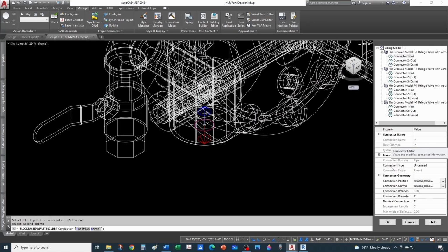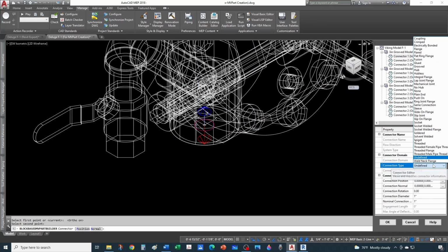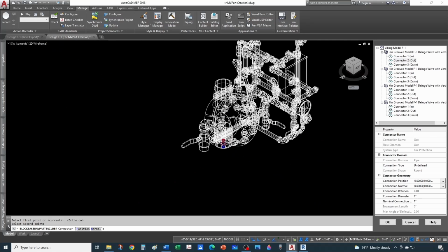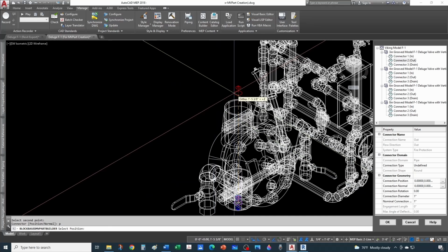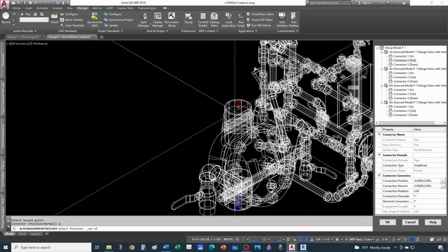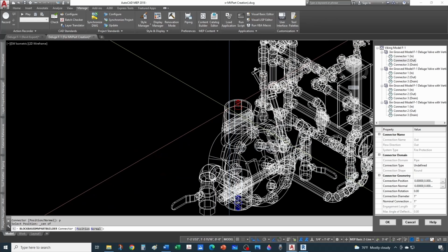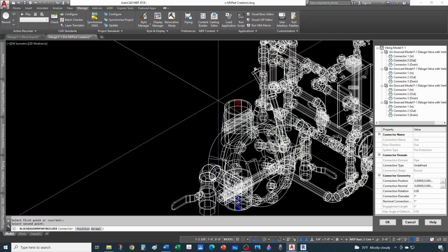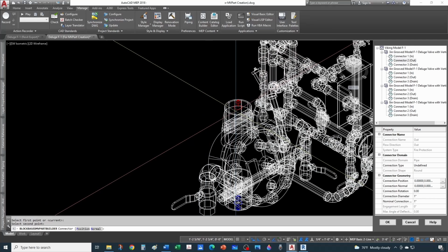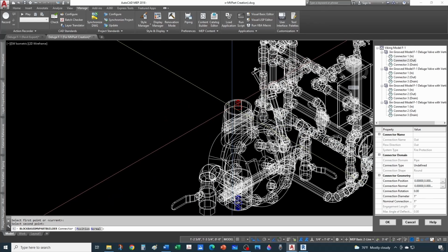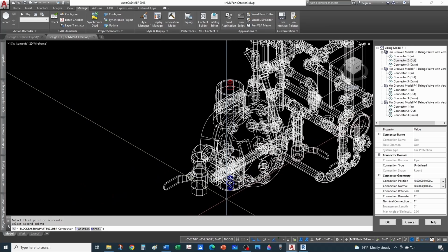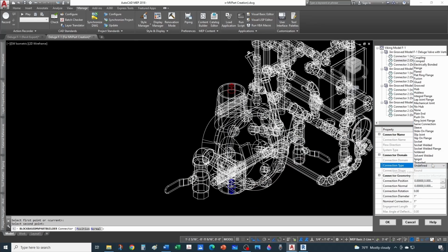Notice that it is set now the connection type as undefined, but we know that this is grooved. Okay, so that's a grooved connector. Now we can go to the out. So for that we go again P for position. We position it in the center, and then normal, you go this way, and notice that you're giving it the direction on which the pipe is gonna grow, not necessarily the direction on which the fluid is gonna enter. Okay, this is the direction of pipe growth. Okay, this is also going to be grooved.